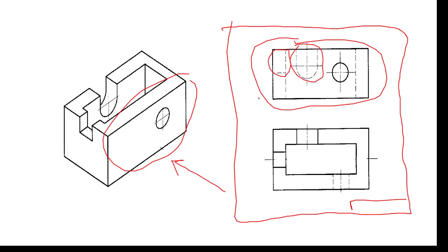Well, at this point, I inform you of another dimensioning rule. It says that if on a view the image of an entity is in dash form, meaning it is a hidden feature relative to the observer, then avoid showing its dimensions on that view. This is a rule and it is strict to obey. Well, after hearing me on that strict rule, think about it.